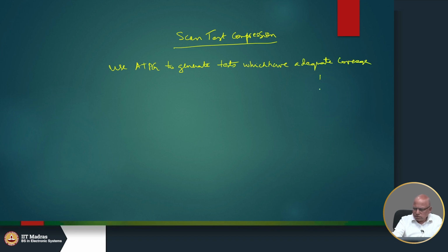So I had the circuit with scan, and I used ATPG, and I got, let us say, some 5,000 patterns, and I had about 96% coverage. Or 98%, whatever. Okay, and I am pretty happy with that. The only thing I am not happy with is that I will need an ATE to store all these 5,000 patterns, etc.